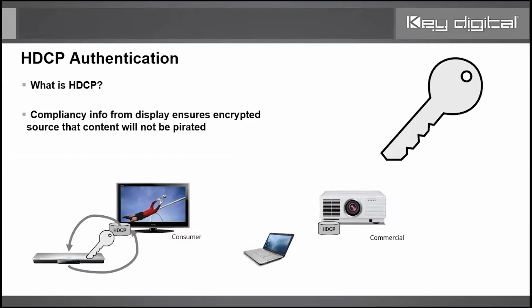What else is built into Key Digital products and fixers? HDCP authentication. Now, HDCP is the real four-letter word of the HDMI world, okay? Well, let's look at the diagrams here, left and right. In the consumer world, you have this HDCP exchange, and what we're showing here on the right with just a laptop sharing a PowerPoint, let's say, on the screen at the projector, you don't get HDCP authentication. Why is that? HDCP is always going to be there on the HDMI connector, on the HDMI cable, HDMI pins.